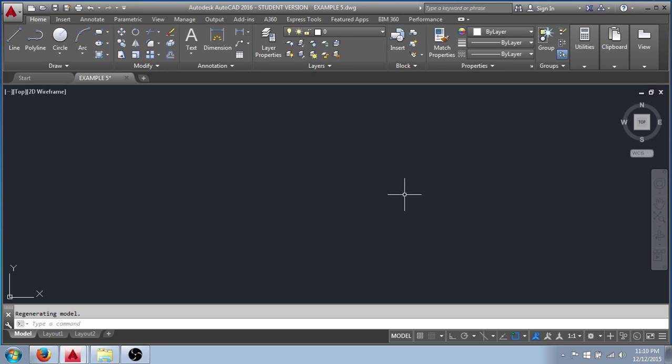There's one other way that we could do a zoom all and a zoom extents. We could do it from the keyboard. I could go Z, enter, and you can see that brings up my zoom tools, and we have an All function right here, and the Extents function is here. I can click on these gray swatches just as I can inside of any command at the command prompt. Or I can also go A, enter, which will select All. Now I could go Z, enter, which brings me back into the zoom command, and I could go E, enter, because that's the capitalized letter here, and that just initiated a zoom extents.